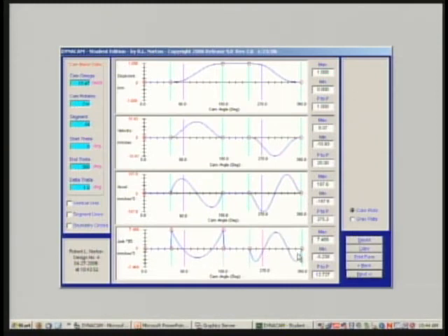The trade-off, and there's always a trade-off in engineering, is that I get a higher peak value of acceleration. You can see that by comparing the peaks of these two. Remember, they're rising or falling over the same time period at the same speed. So all other things equal, they'd have the same peak acceleration. But the different functions give me different peak values, different shapes of curves.